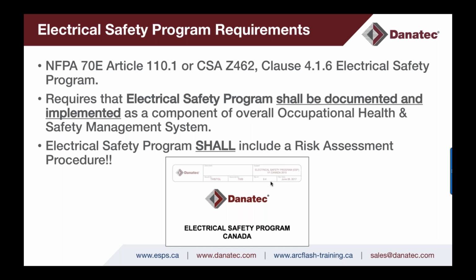So your electrical safety program shall include a risk assessment procedure. That is also in 70E and Z462. So you have to identify the risk assessment procedure.